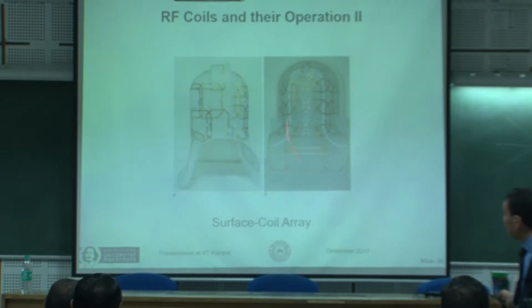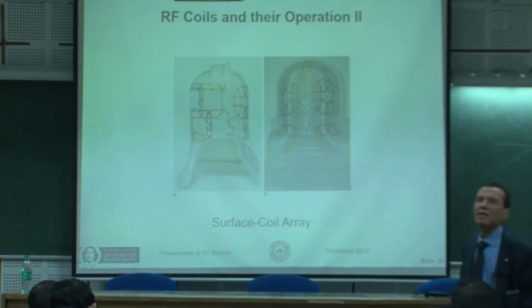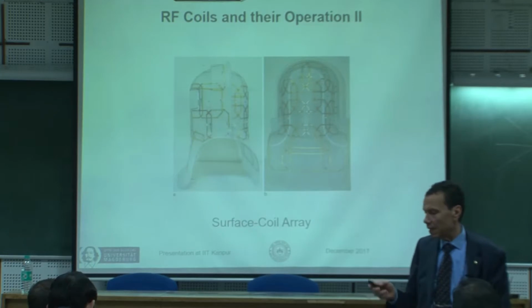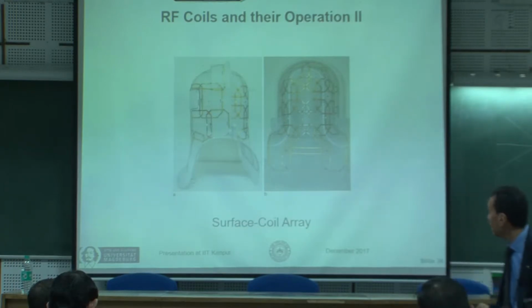And the whole idea here is very similar to the work of antenna array. Of course, if we have a 1 Tesla system at 42 megahertz, it is not microwave, it's in megahertz, but nevertheless, the main theory and the main algorithms we use are similar to the antenna array.